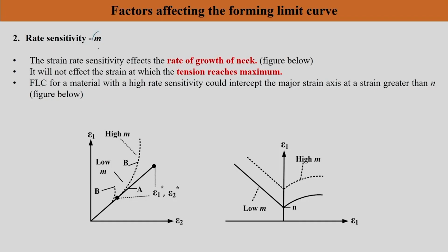Okay, m. So we say the strain rate sensitivity index m. This comes into picture when you go for, let us say, C epsilon dot power m, and we have also studied that this m actually controls the post necking behavior, that is epsilon u minus epsilon t minus epsilon u. That particular region in the stress strain behavior it is going to affect.